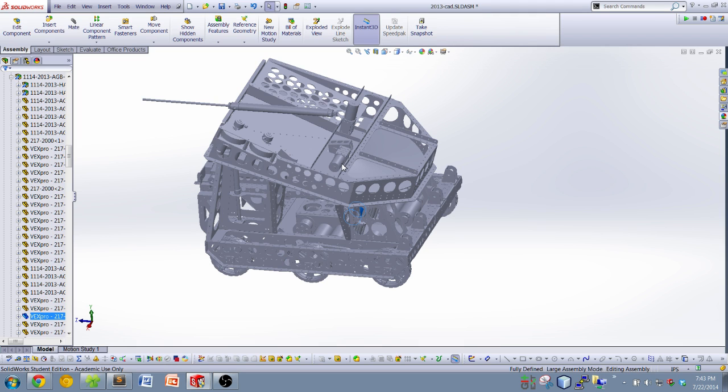So it's no longer saved as an individual SolidWorks assembly file and SolidWorks parts files. The step doesn't keep all of that information, because a different program, like Autodesk Inventor, is a different 3D modeling program and has a different way of saving all the color and features and mates. Step just gives you the parts and their locations in space, and that's about it. Some people will upload the entire SolidWorks files, some will upload the entire Inventor files if they use them, but not every team does. They're bigger, larger, and harder to do.